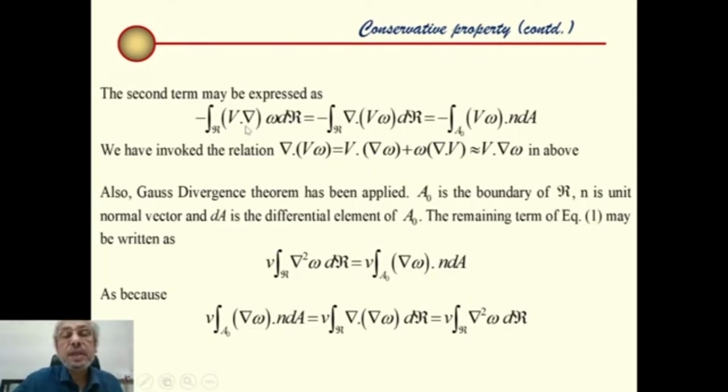Now this is a subtle mathematical expression. Certain operations have gone in. If grad is operated over v and omega, we can write v dot grad omega plus omega into divergence of v. Simply expand grad dot v omega. Now if we expand this way, for incompressible flows, this part, divergence of v, is 0. So we can drop this.